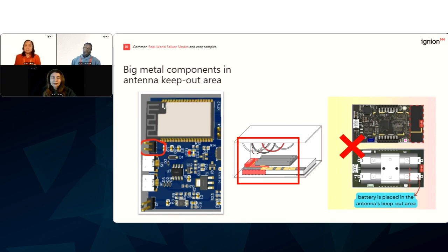Indeed, when you're designing these antennas into your product, the first thing you want to do is confirm performance with us, via simulation, for instance, right? And just ensure that any metal components are as far away from the antenna as possible. And in fact, there are rules to that, right? And you need to follow those rules according to design guidelines.